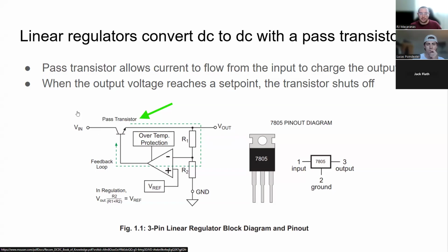Right? And so in that sense, these linear regulators can really only step the input voltage down. So if I have like a 2-volt battery, but I need to increase that voltage, the linear regulator is not going to do that. You're going to need to use some other power regulator, in that case, voltage regulator. In that case, it'll be some kind of switching regulator, not a linear.